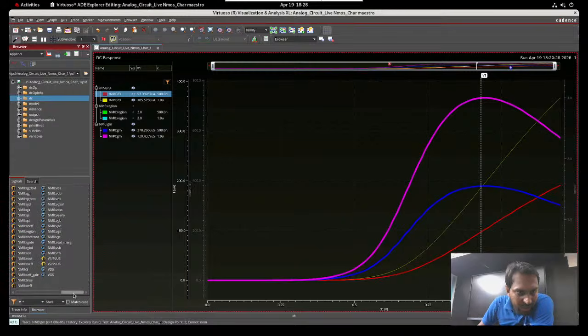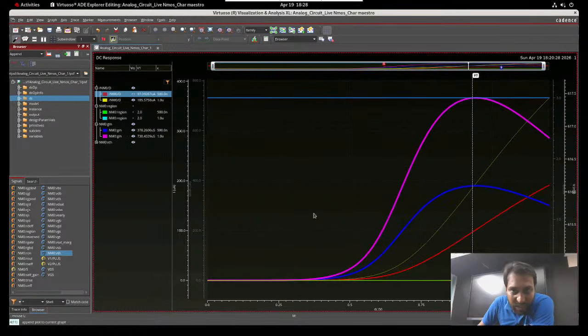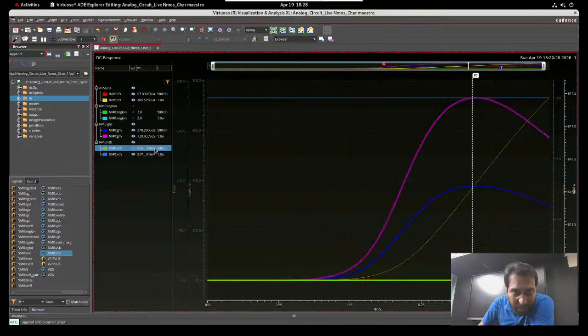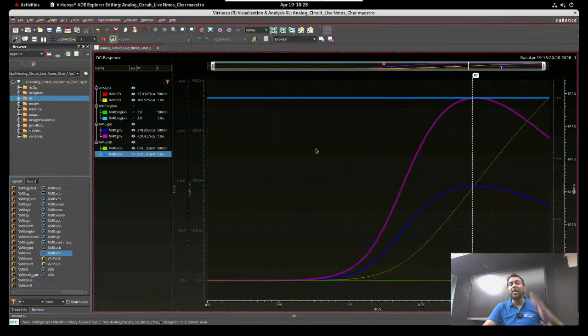You can check the VTH also. That parameter is important. VGS is an important parameter too: what will be the region, what will be the gm. These are very important parameters. If you talk about 500 nano, that's 614 millivolt, and for 1 micro that is 617. So don't think it is a lot of change, it is a 3 millivolt change.